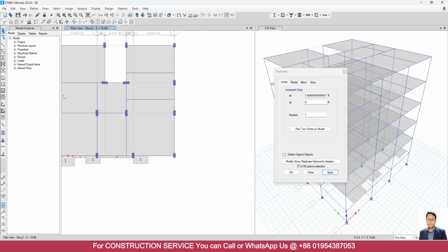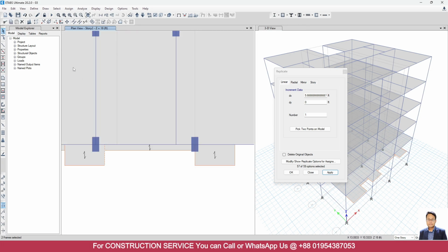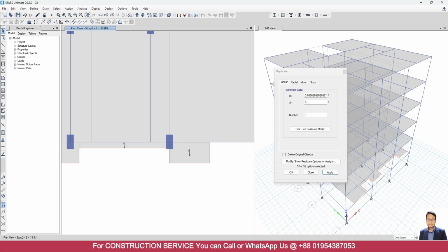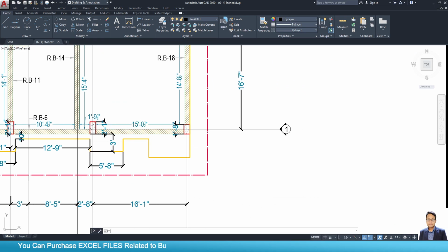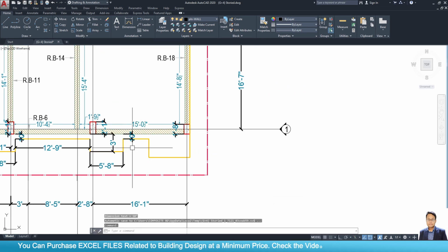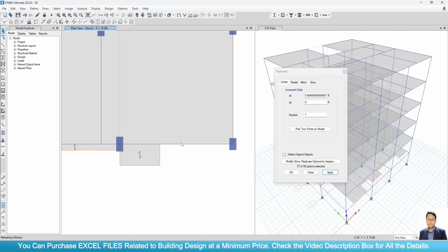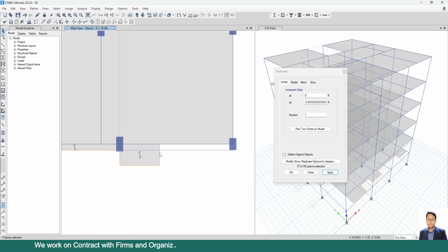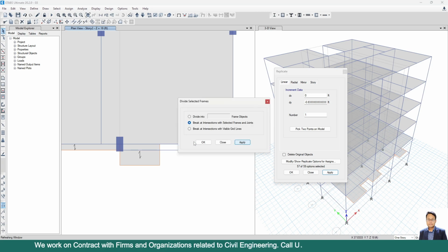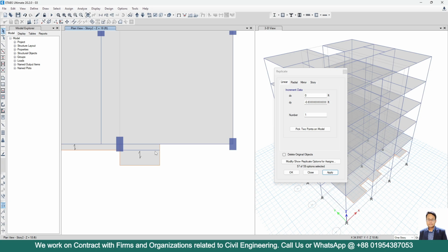After that, okay, here we can join these two frames, right? So select them and go to join frame. Again, we can see here we have a distance of 10 inches maybe. Then we have a distance of 4 feet 5 inches for x direction. Select this one, 0, -10 inches, apply, select this one and this one, then divide the frame, delete the unnecessary structural beam.